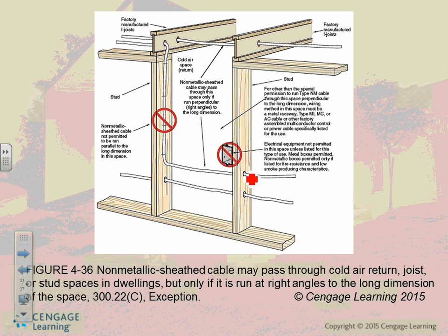Okay, now with the dual studs, the 2x4 studs, sometimes you use the cavity between the studs as the return for the air, not the supply. The supply is always ducts. They put a duct to heat. But the return, the air that you push, has to come back and be circulated.